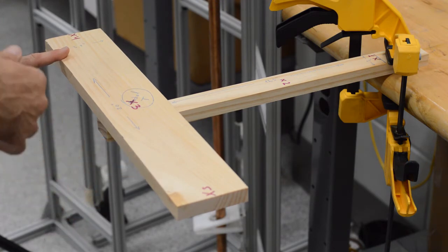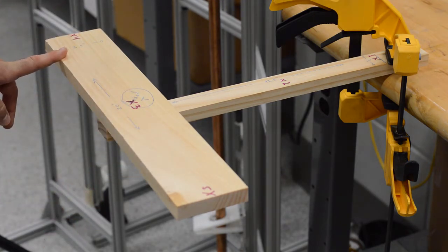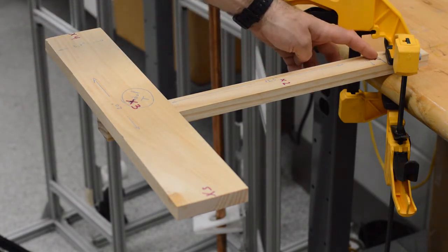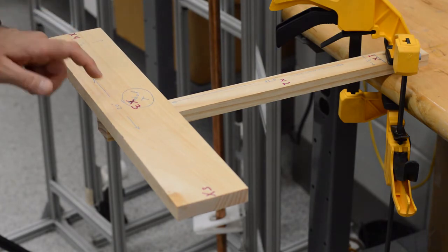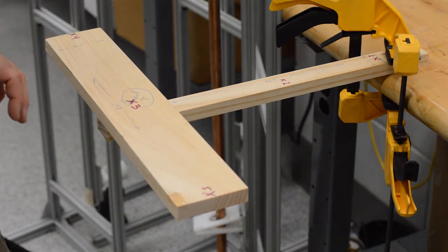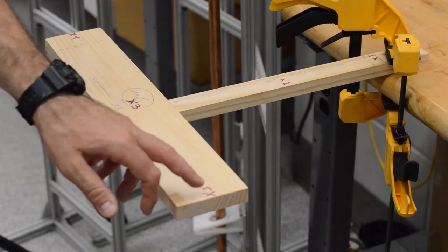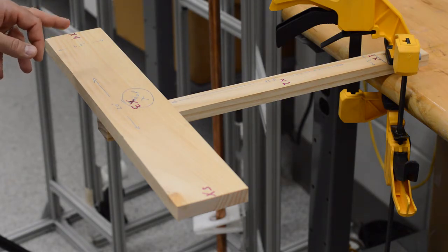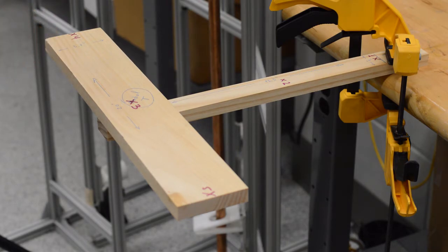So, in order to obtain this, we can go by with only 5 accelerometers or tapping points. So this is 1, 2, 3, 4, 5. For the hammer test, we were going to use only 1 accelerometer, maybe at this point. And for the shaker test, we are going to use 5 accelerometers with 1 application point of the force.